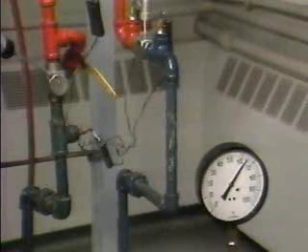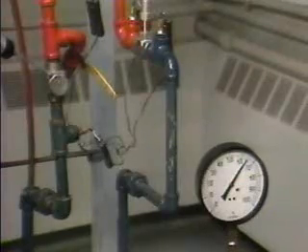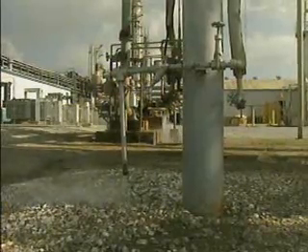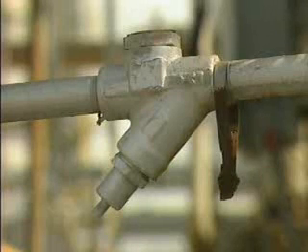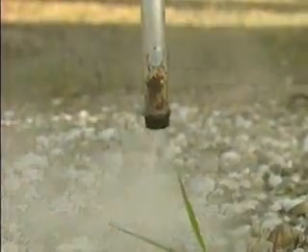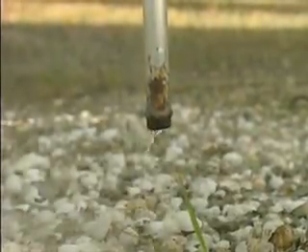The back pressure at the trap outlet should be checked to make sure that it's not too high. If there's no gauge downstream of the trap, you may need to install a temporary gauge so you can check the back pressure. For most thermodynamic traps, the downstream pressure should not exceed 70% of the upstream pressure, but the manufacturer's instruction should be checked for the allowable back pressure for a particular trap. Increased back pressure will cause the trap to cycle open and closed more frequently, and it also reduces trap capacity.